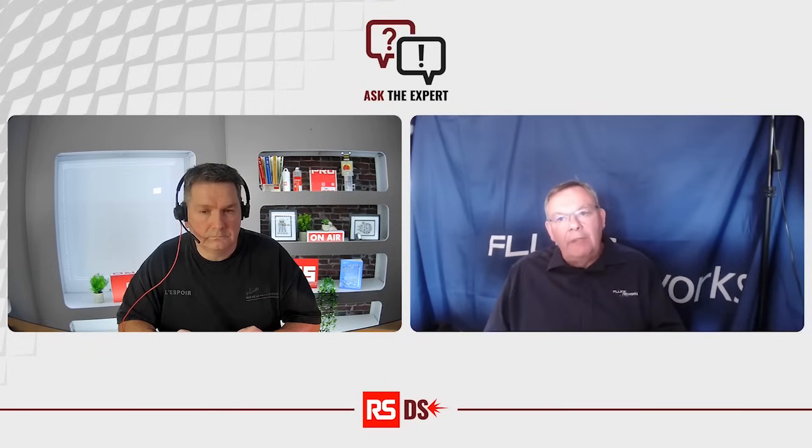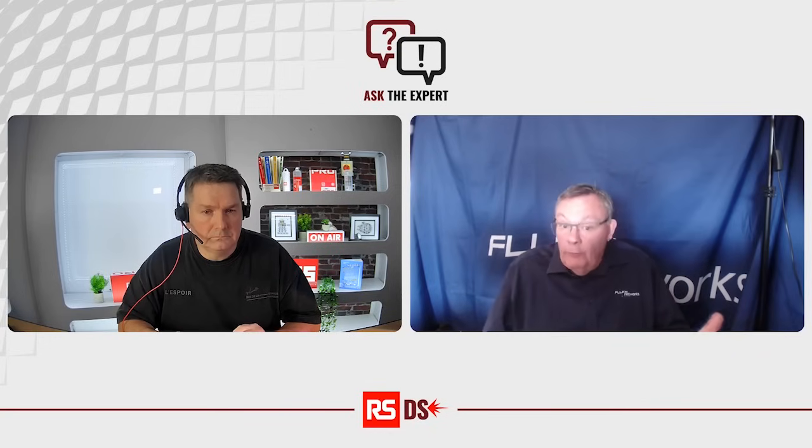With the CCTV camera, we're going to install it, or we are installing it on the end of a piece of cable which is already in the building. We may be reusing a cable, or we may be using a freshly installed cable. But what we need to know is, does the cable have sufficient bandwidth to support the gigabit network connection which the camera requires?